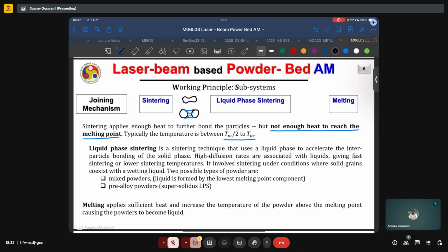However, there are other considerations in place, such as coarsening, in which case a large particle will continue to grow larger, while a small particle will just end up getting eroded. But this is the basic principle. The reason we are applying heat for the sintering process is to enhance this diffusion process.